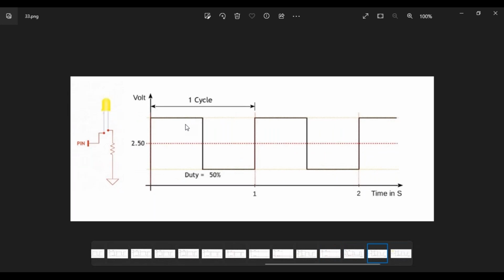You cannot take 1 hertz, or 2 hertz, 3 hertz. So keep it like 100 hertz, 200 hertz, 300 hertz. Sometimes we have 5 kilohertz, 10 kilohertz and so on. So that is how fast the switching is happening, and you will feel as if there is a continuous voltage being delivered. Is there a minimum frequency we should select?